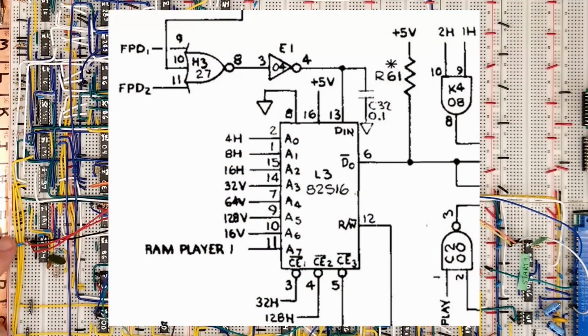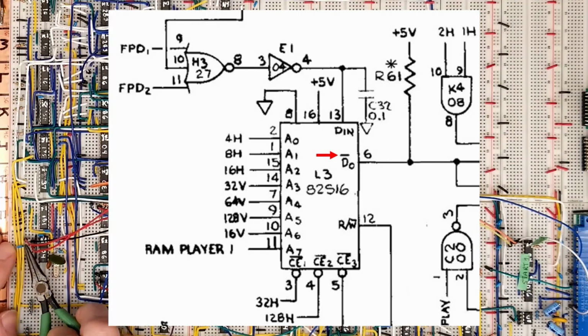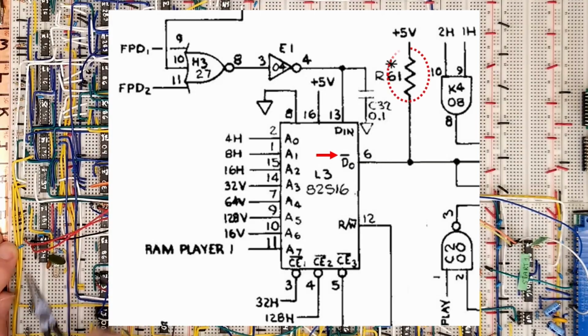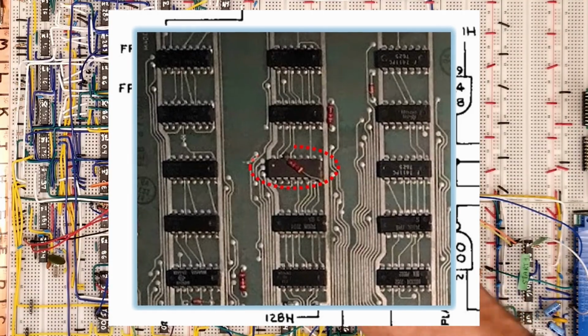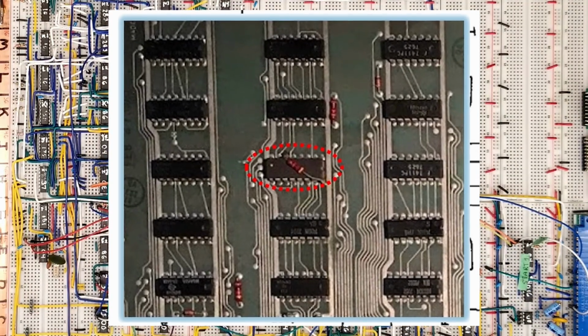The data outline is inverse of data in. Kind of strange design, but for the output they have open collector versions that can be tied together in an array. Open collector outputs only drive low, so they must be pulled high. Hence our addition of the optional R61 on the schematic. You see many boards with 1K resistors soldered above the chip. I'm assuming they sometimes use open collector parts to expand their sourcing options.